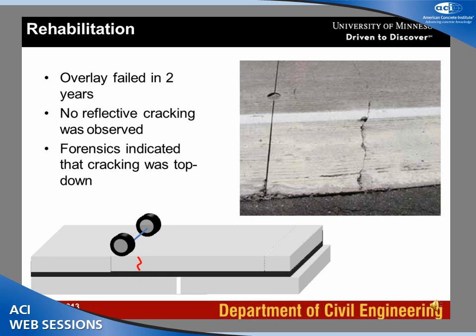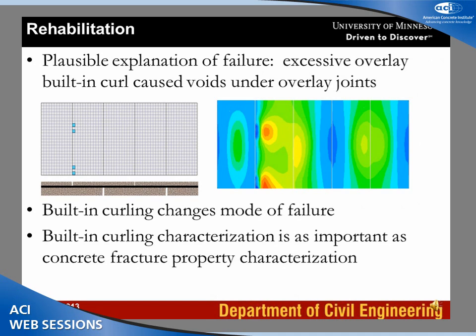So we decided to conduct a very simple finite element simulation. We used iSlab 2000, and we modeled the overlay using plate elements. For the interlayer, we used a spring layer, the Winkler model, and another plate layer for the existing pavement. You see many joints here, but some of them are just the way iSlab models them. Some of them are rigid, so basically there are no joints. It allows modeling mismatching joints. And the result was mixed.